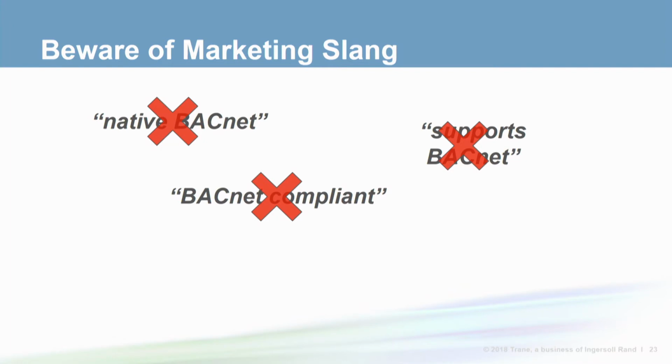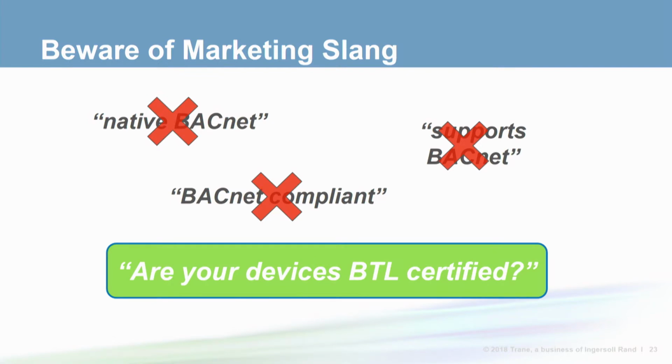Often they are used in hopes that you are not educated enough to ask the question, are your devices BTL certified? If the answer is yes, you can ask for their certification document or go to the BACnet International website to verify the device is listed. If the answer is no, I'm not saying that you should immediately disqualify that device, but there is more inherent risk, and I think you owe it to your customer to do a little more digging.